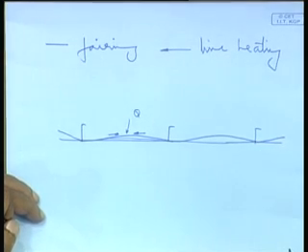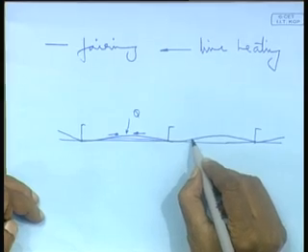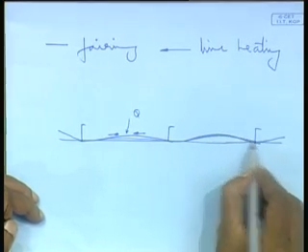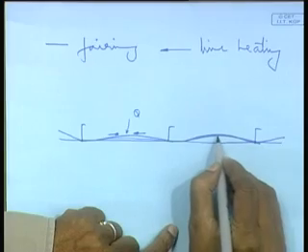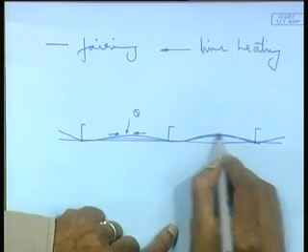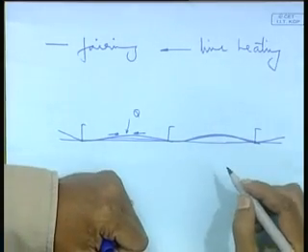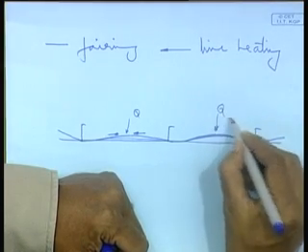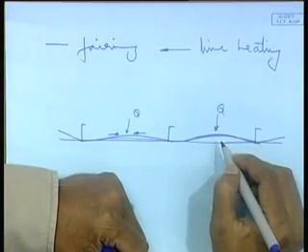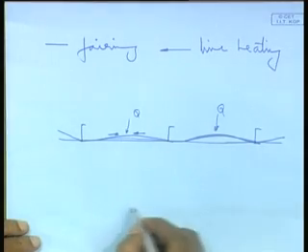It will tend to flatten out. Because it has buckled in this direction, what does that mean? The plate has elongated at this edge. On this surface, the plate has elongated. Now I shrink that. How can I shrink? The same way, I apply heat. How will it shrink when you apply heat in this fashion?